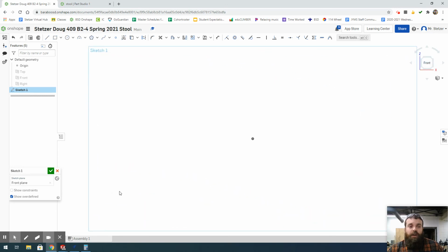From this front view, I'm going to start by just using my line tool and creating a simple trapezoid. So I'm going to click line. I'm always snapping to that center point. We can see in the lower right corner we have a coincident constraint command, that little T shape, that says that they're stuck. No matter how far in or out we are, they're magnetized and glued together.